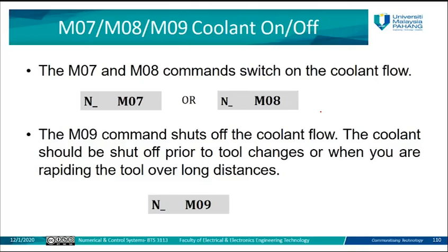When we lower the temperature, we increase the lifetime of this tool. Otherwise, if it gets a very high temperature, maybe you use it 2 times, 3 times, 4 times, and it's broken or already damaged. So in the CNC machine, they have to use a coolant, and this coolant will spray some liquid to lower the temperature of the tool.